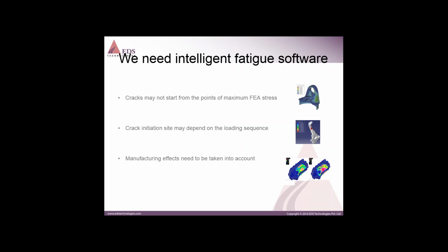And we have seen FE stresses are only one part of the story, whereas loading is the other part of the story. And also sequencing and manufacturing effects are very, very important when it comes to fatigue analysis and fatigue life.